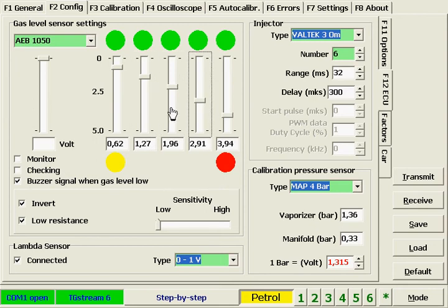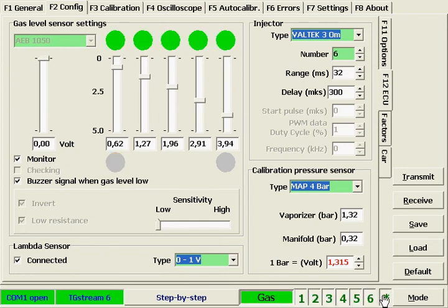The sensor must be on and installed. Turn the option of monitor on and check the actual work of the indicators. Switch to gas mode and make sure that the information transmitted about petrol is correct. In this case, we can see that we can't reach the red indicator of the lowest level. That's why we must switch the monitor off and regulate this level.